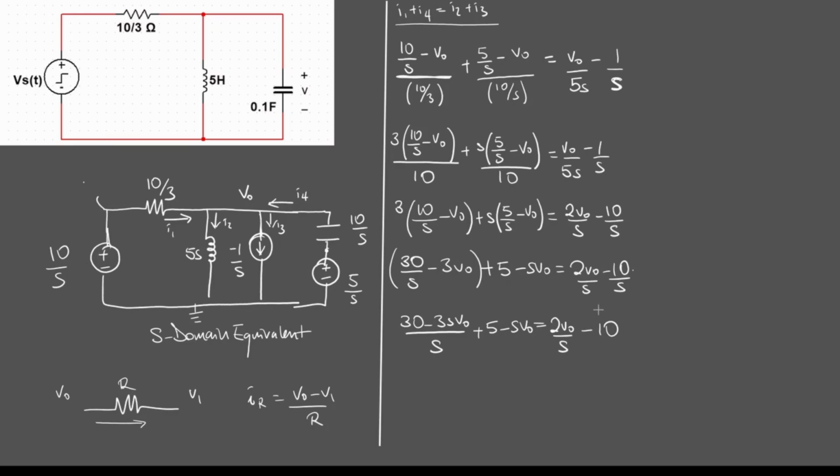Let's multiply through by 10 minus 10 over s. So now we're going to multiply through by s. The usual expert advice when solving with Laplace transform is that you're always going to have a couple of denominators if you'll be using nodal analysis. So where you can, clear your denominators so you get closer to linear algebra as you can. As you see, once we came here, we cleared with 10.